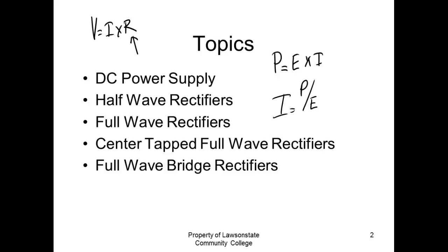You check the connections. Because if you got 1 ohm, 12 amps would drop 12 volts, right? And if you drop 12 volts in your conductor, how much is left over for your starter? None. So if your car don't crank, you don't go out there and change your batteries. One of the first things you do is what? Check the connection. Then you check the water, of course.